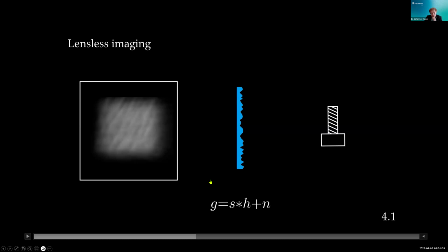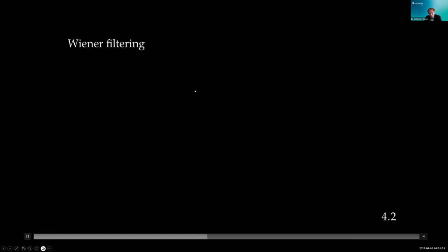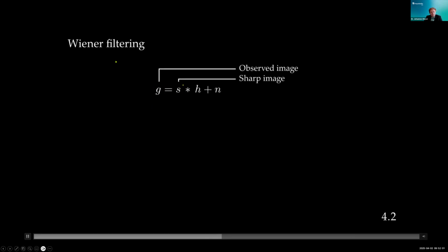But still, you might ask yourself, how is it now possible to extract this S in which we're interested in from this blurred observation on our sensor? And maybe then you might go further back in the things you remember from your first image processing lectures, and you might recognize that there was this thing called Wiener filter that allows to do exactly that, extracting a hidden signal out of a blurred observation, which is generated by a convolution of the signal with some kind of point spread function.